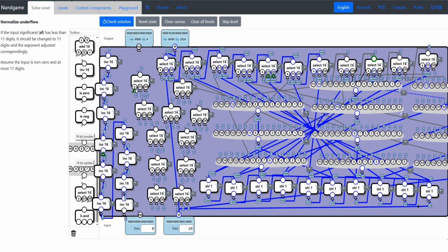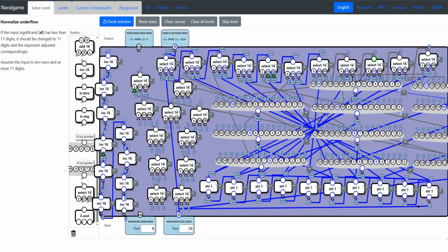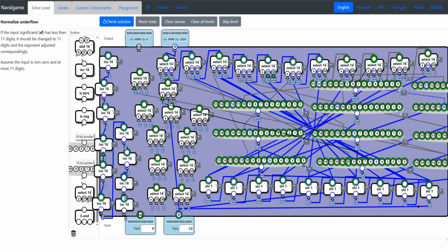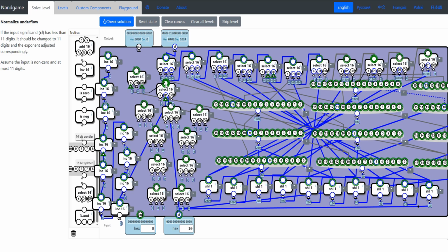All right, so we're doing the same thing on this first selector here. We're gonna check the value of the 10th bit of this bit splitter, the one that's not being shifted at all. If it's 1, actually, we don't need to hook that up to anything because we want to output 0. It means we haven't shifted at all. Then we'll take this second one, hook that up to the bit splitter for our 1 shift left here. And if that is a 1, that means we want to shift left once. So we'll hook it up to this first increment that is a 1. Hook up D1 there. And then on the previous one, we have to hook up D0 to that second selector.